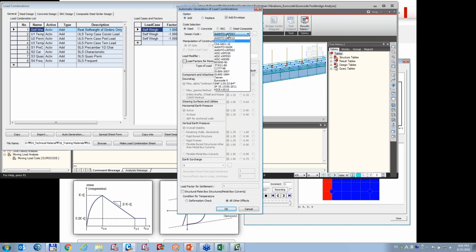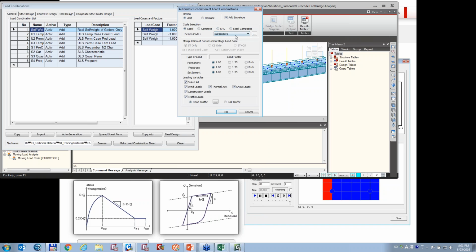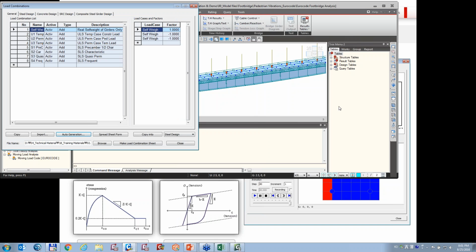In the load combination, the 100-30 rule can be automatically considered in Midas Civil, but for the Z direction combination, manual combination will be required.